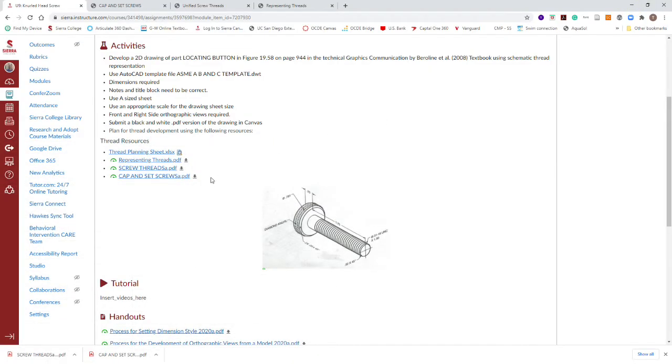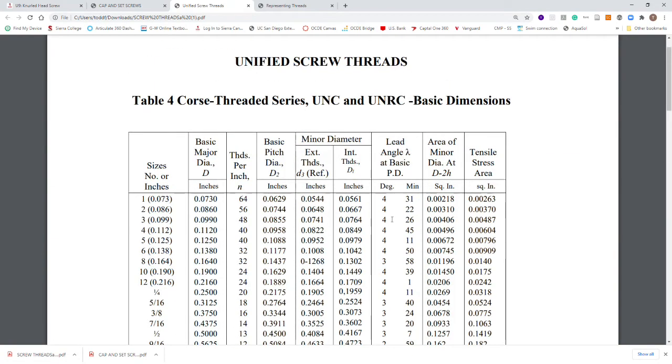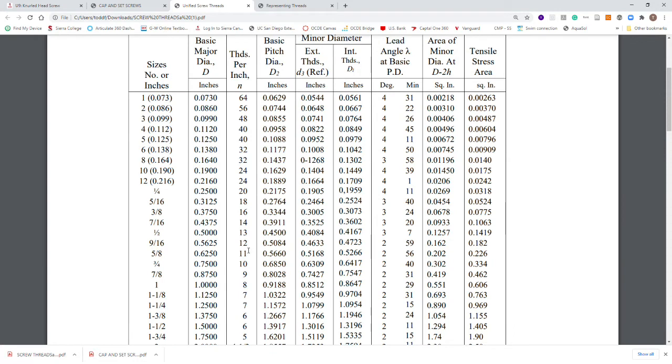So we're going to go back to our screw threads. So we need to go to the UNC chart. And what they're calling out as a 0.31 is actually a 5/16. So the nominal size is actually 0.3125. So if we were to do this to the chart, or to the sketch drawing, and this was a military screw sold in the military, you would call it out as a 0.31. If you were to go down to the hardware store, it'd be a 5/16 18 screw.